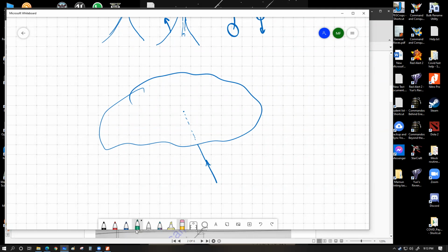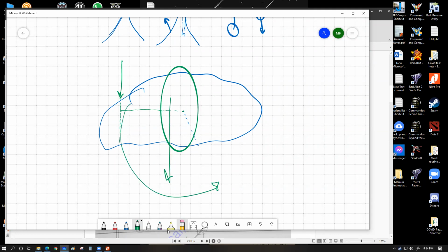But if we apply a force that is offset from the center of gravity point, let's say if I apply a force maybe somewhere like this, so forget about the previous force right now, which is definitely not going through the COG, in that case we're going to have a bit of moment produced on this object, and that's also going to cause the object to move forward, which means this force is going to cause the object to have some acceleration in this direction, and at the same time this object is going to start an anti-clockwise rotation. So it's going to rotate and fall down, in this case down, because I've drawn a vertical downward force.